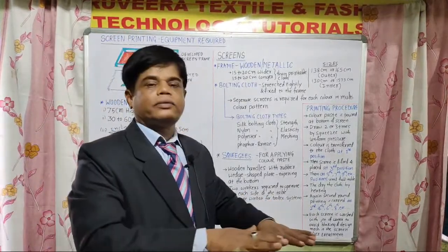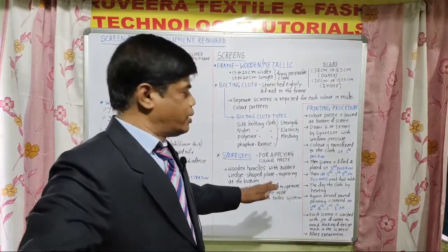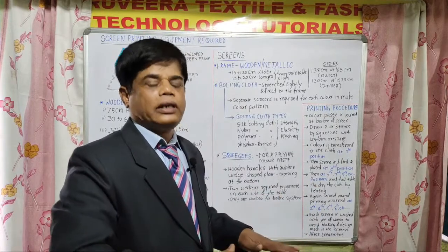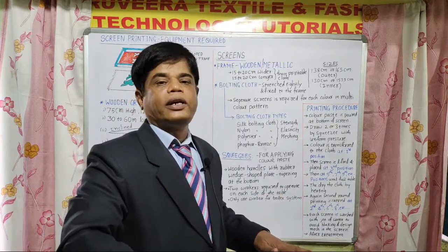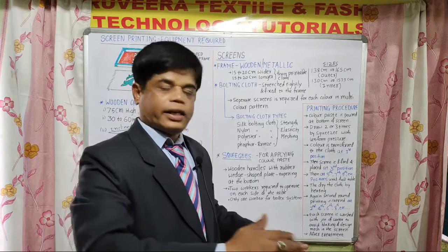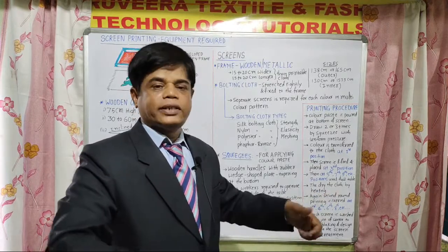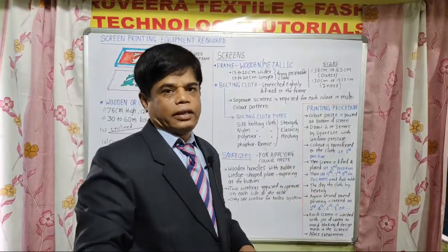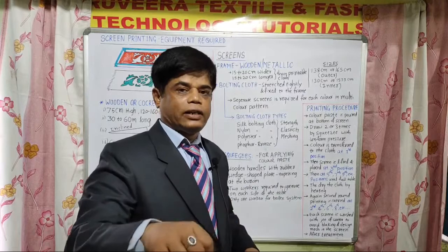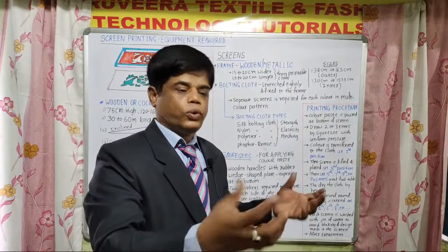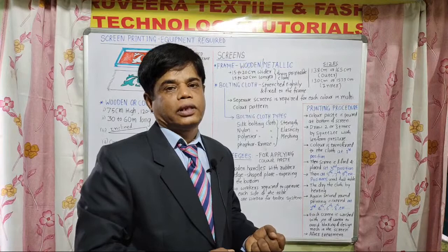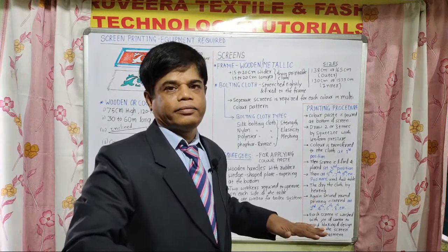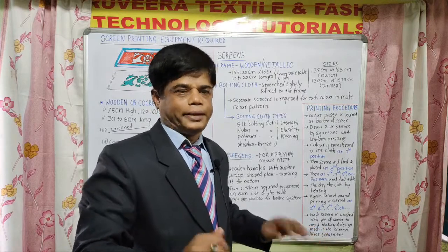The printable cloth is stretched on the whole length of the table, and to avoid floating, creasing or folding of the fabric, it is stretched lengthwise and widthwise and fixed by means of a pin. The felting cloth and the gray cloth help to hold the cloth which is going to be printed, stretched and flat. Hope you have understood what I am saying.